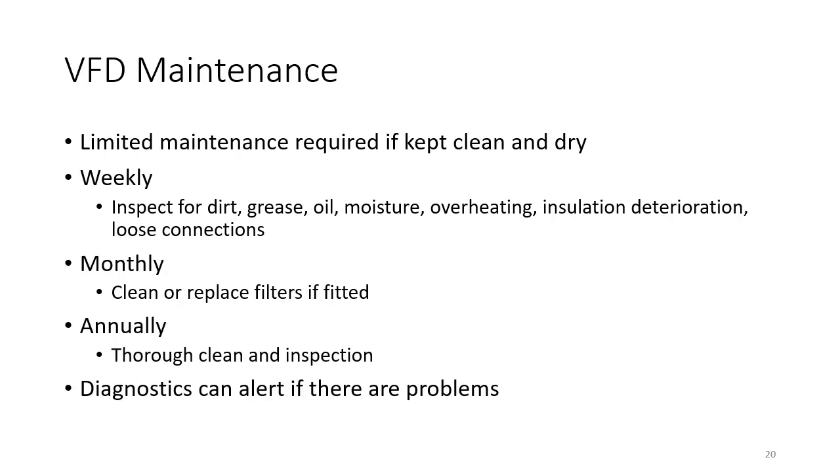In contrast, VFDs need very minimal maintenance. There would be various inspections like before, so typically weekly. You might inspect for dirt, grease, oil, moisture, maybe overheating, insulation deterioration. If there's vibration, that could be causing loose connections, but generally they don't need much maintenance as long as they're kept clean and dry. Now there are fans, so you might need to clean or replace air filters which protect the fans. That will depend on if the VFD has those or not.